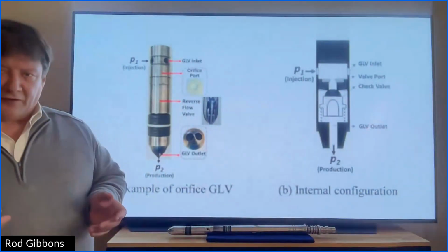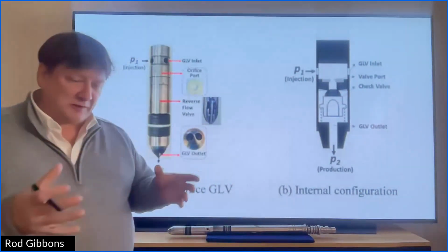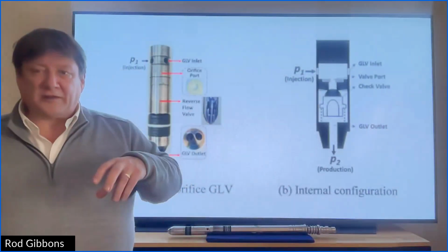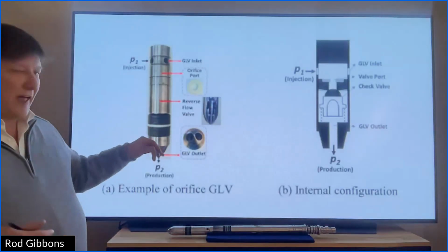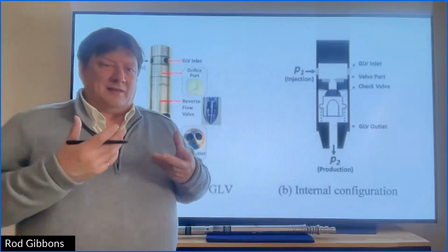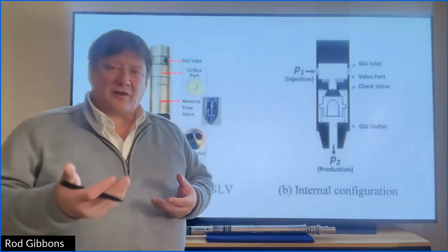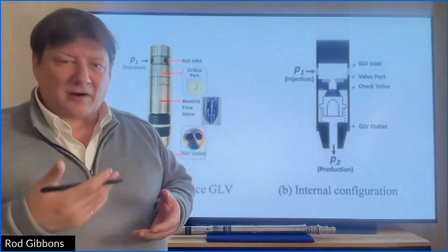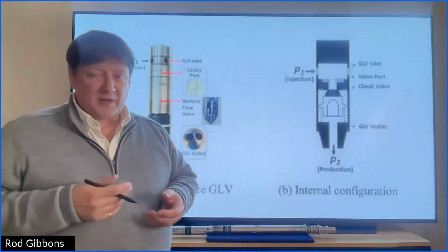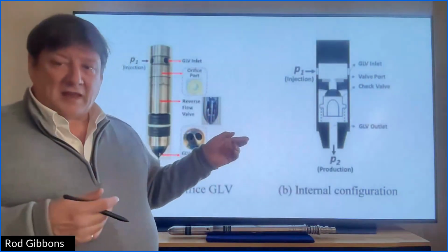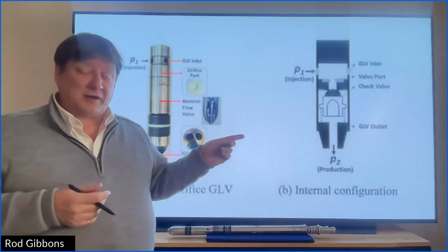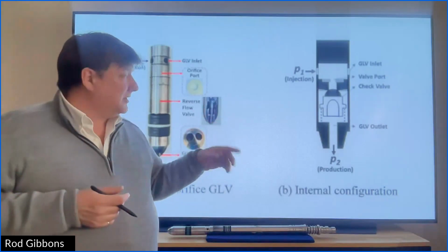So then you have your valves. So we got our side pocket mandrel. That's where that stays in the tubing. It's screwed in. It's run with the tubing. The valves, again, a general philosophy: if there's something that has a lot of wear, a lot of use, it's great if you can retrieve it and change it out. So with gas lift valves, you don't typically have to pull the tubing to pull the valve out.